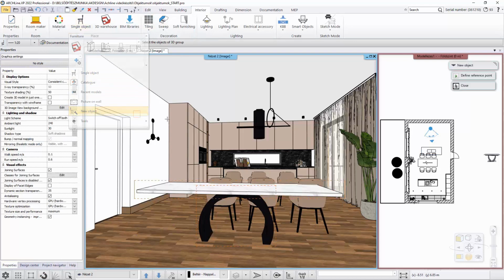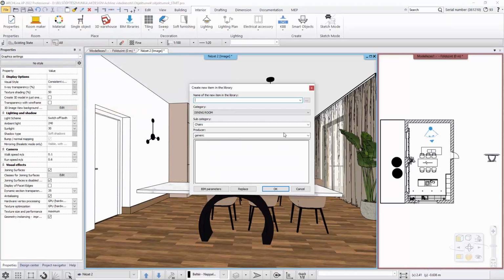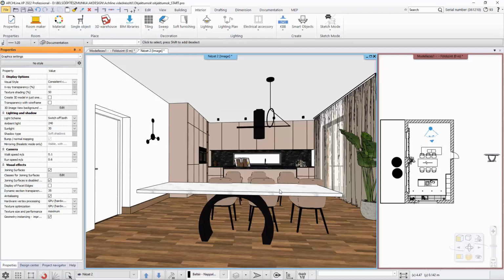As we can see, these elements are still shapes, not objects. The table will be saved as an object. Select the foot and tabletop and save it to the object library as a table with the interior menu, Object, Create Object. You can also delete these parts, as you will no longer need them.